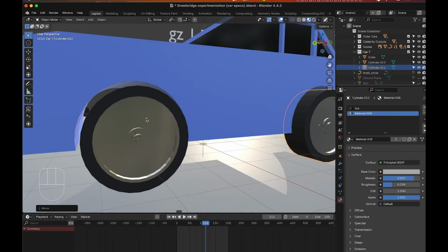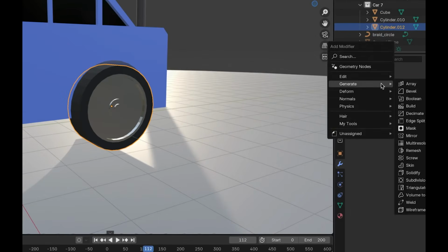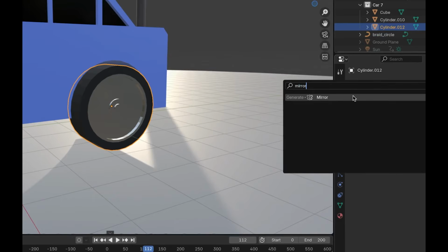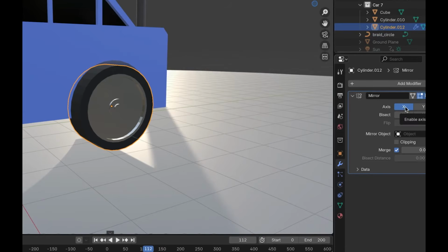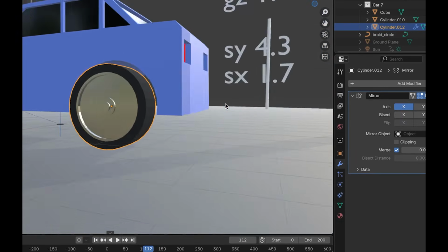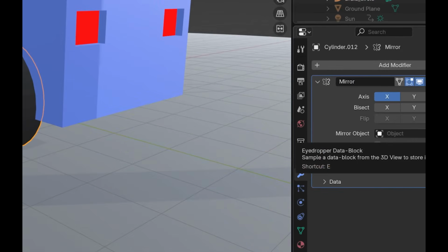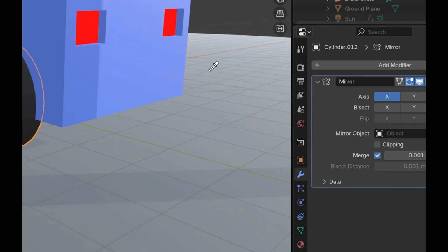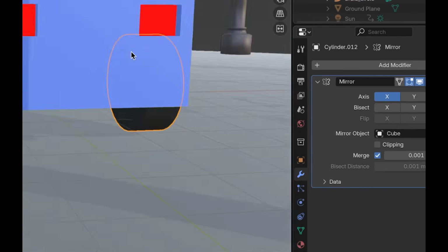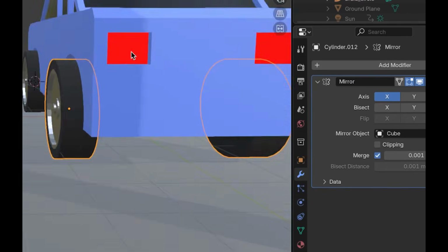We're going to add a mirror modifier to each of these. We know how to do this, right? Blue wrench. Add modifier, start typing mirror. And it's a little different this time. Yes, x-axis, but right now it's mirroring upon itself, which isn't going to be apparent. We want it mirrored on the other side of the car. So for mirror object, do the eyedropper and click on the car. So now it's mirrored on the x-axis on the other side of the car, specifically, okay?